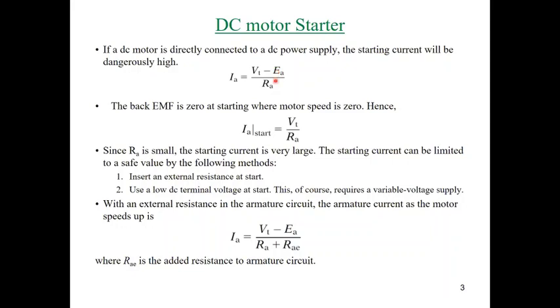The armature resistance is normally a very small value, in particular for high rating machines, so we expect a very high current at starting. This is a problem in DC motor. We will see in the examples how much the starting current is in numbers to recognize its effect. So we have high starting current for DC motors. How high it is, we will see in the solved problems.